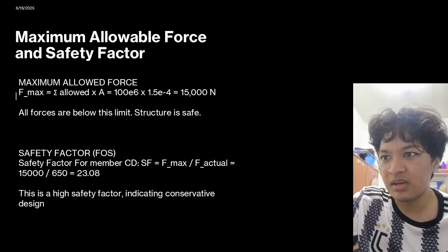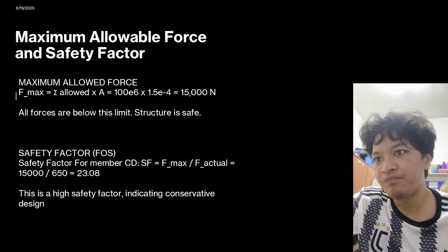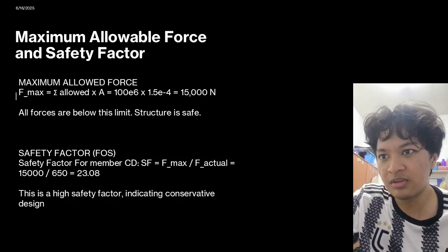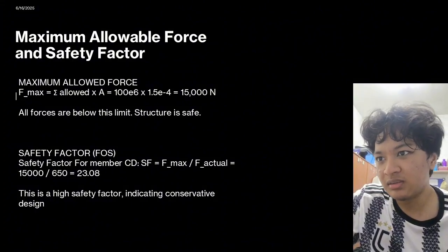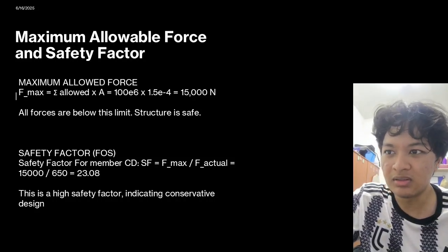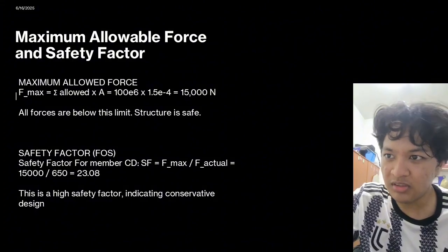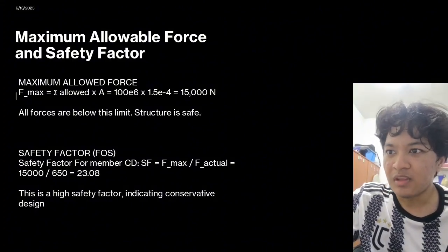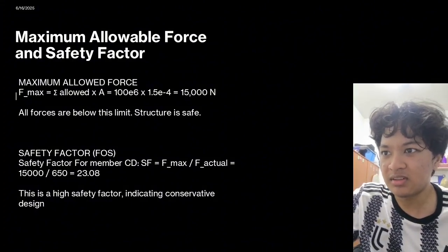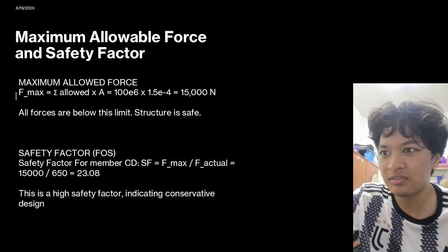safe. And for safety factor, we take for member CD, SF equals F max over F actual, and we take 15,000 Newton over 350, and the answer is 223.08. This safety factor is very high, indicating a conservative design.